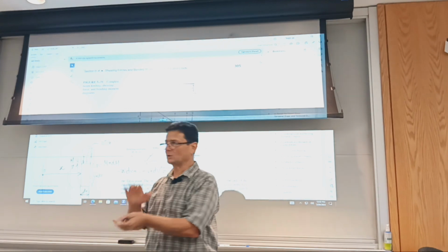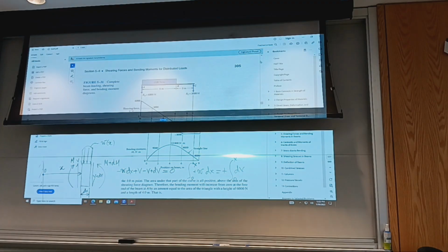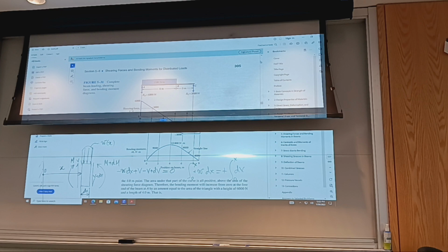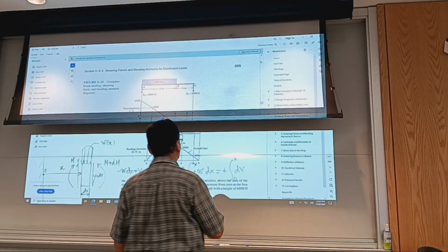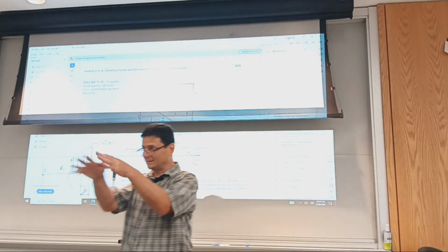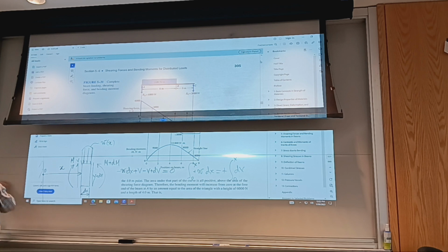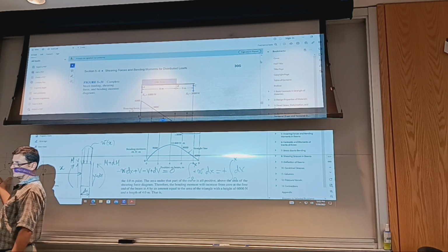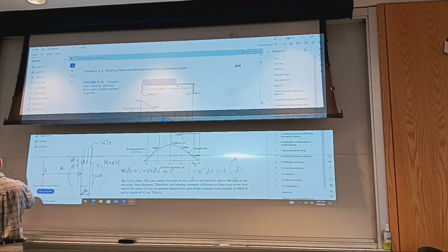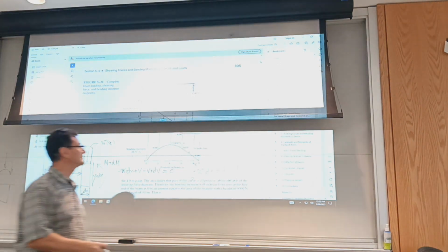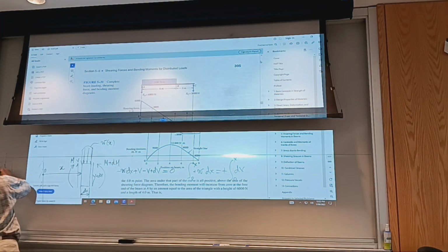Actually, it's a good approximation of contact forces, because concentrated forces are an idealization. In actuality, it's spread over a short area. So if you have a pulley on a shaft, and there is a force coming from the belt, you actually have an area of distributed force over the width of the hub. Does it make sense? It's not, again, a concentrated force applied at a point, that's an idealization. And if you want to go to an extreme, you can assume all forces are distributed.